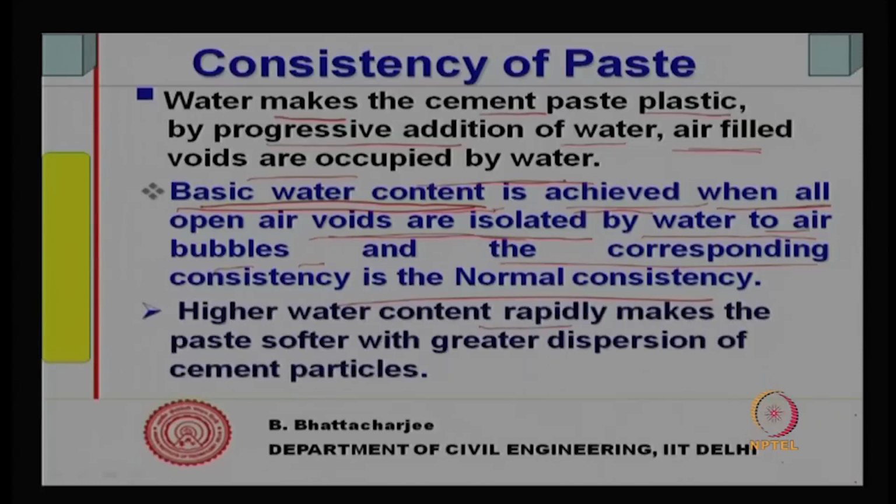If you add more water, it makes the paste softer and greater dispersion of cement particles may occur. So, cement particles can also get separated if you, of course, use a dispersing agent, otherwise the possibility of getting separated exists.